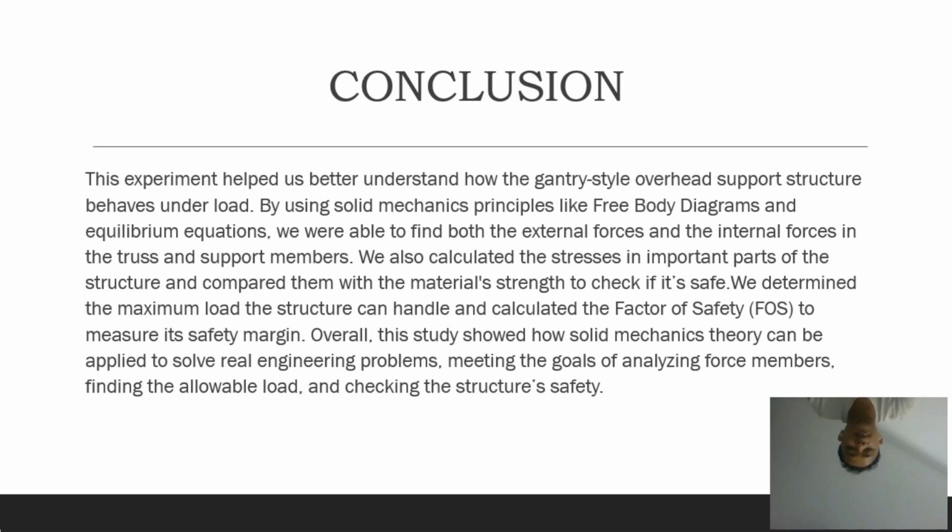By using solid mechanics principles like the free body diagram (FBD) and equilibrium equations, we were able to find both the external force and the internal force in the truss and support members. We also calculated the stress in important parts of the structure and compared it with the material's strength to check if it's safe.